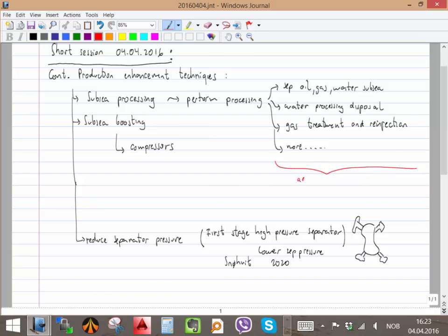And then you can also address some advantages. For example, if you have problems with slugging, you have these transients and they're causing a lot of problems, back pressure on your wells, you can eliminate some flow assurance issues. If you have, for example, water separation, remember that water is what causes hydrates, and if we take it out of the equation, then we don't have any problem. So it helps to eliminate, or at least to mitigate, flow assurance issues.